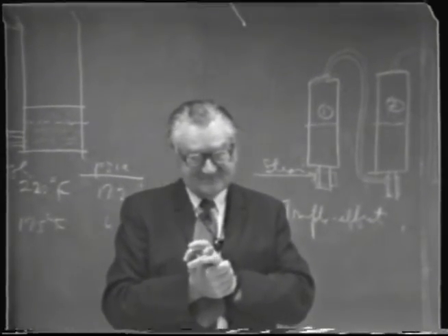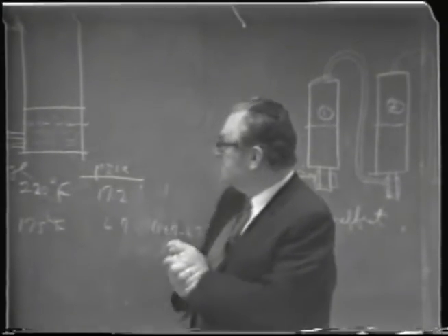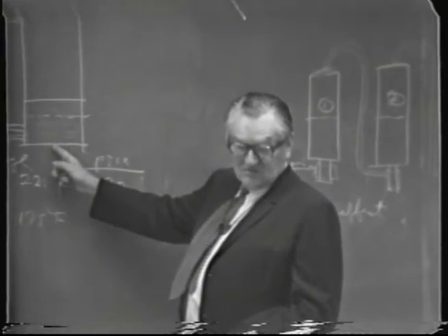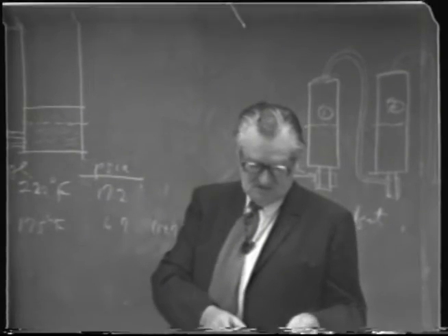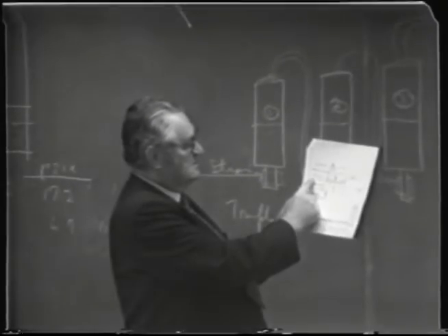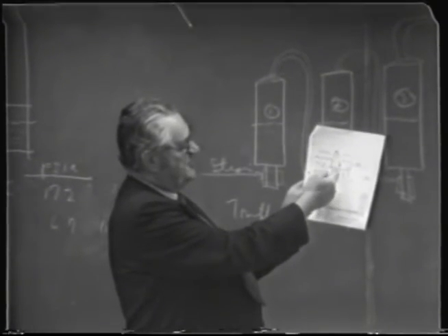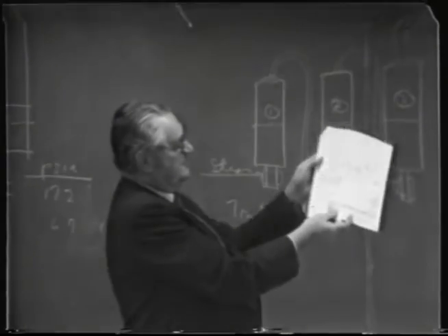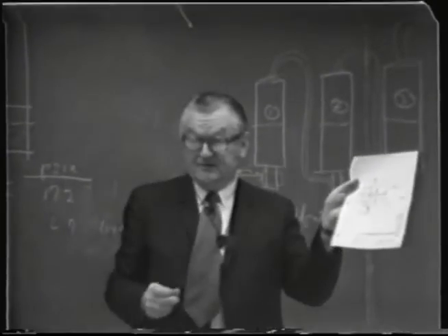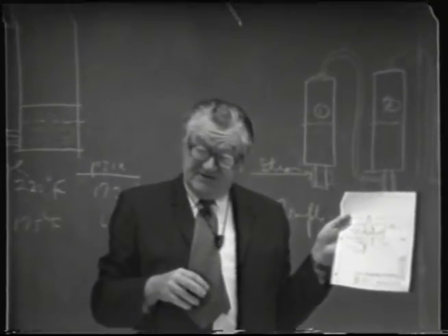Question? What does the motive steam do, and where does it go up there? Does it go in with the stillage? No, it doesn't. In this case, it doesn't go into the stillage at all. It goes in here, and the vapor that's flashed off of this stillage comes down through that little dotted pipe, and that's where it mixes with the ejector.